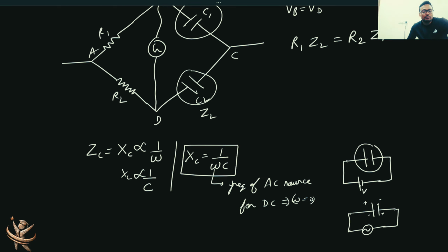So current is never going to be zero. So the higher the value of frequency, it's like not even 10% charged, and immediately you change the polarity, right? So you keep on fluctuating the potential across the capacitor. So the capacitor will never reach its maximum charge state, where current becomes very weak or becomes zero.